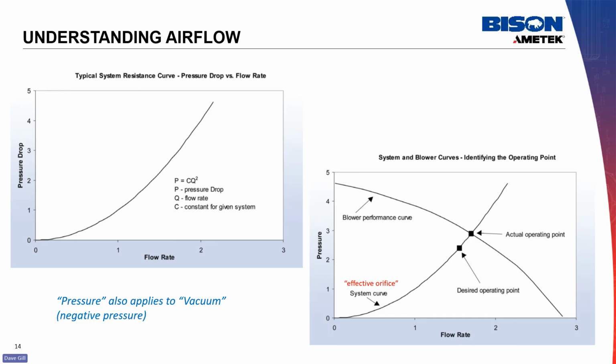The air performance of a blower is plotted with pressure on the vertical axis and airflow on the horizontal. In selecting a blower, the designer needs to determine an operating point. This is based on the impedance of the housing that the blower works in. It includes the airflow rate required for the application, along with the resistance to flow that the system will impose. When a flow curve is plotted with the impedance curve, the intersection defines an operating point. From this, an appropriate motor blower can be determined.